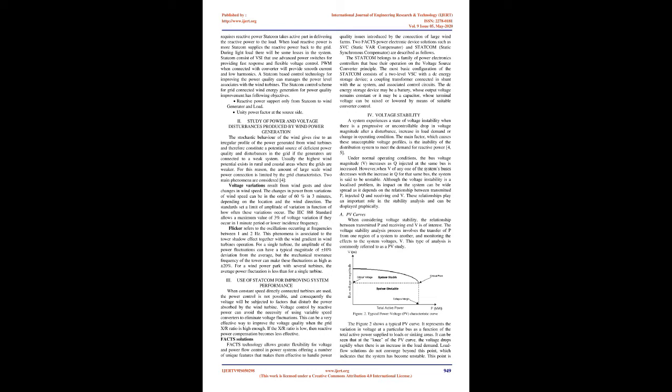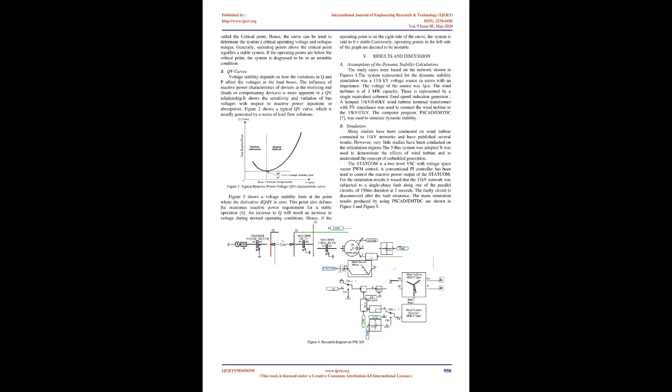FACTS solutions. FACTS technology allows greater flexibility for voltage and power flow control in power systems, offering a number of unique features that make them effective to handle power quality issues introduced by the connection of large wind farms. FACTS power electronic device solutions such as SVC, static VAR compensator, and Statcom, static synchronous compensator, are described as